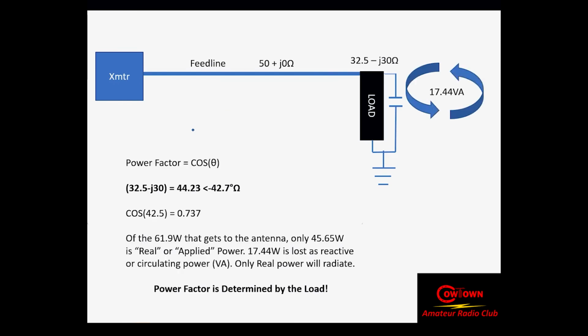All right. Now we get to the phase angle. This is the one that bites, and it bites really hard. It's called power factor. Power factor is essentially that ratio of real power to apparent power. Remember the glass of beer. The foam on top was reactive, the liquid beer was the real, and the combination of the two is what we call apparent power.